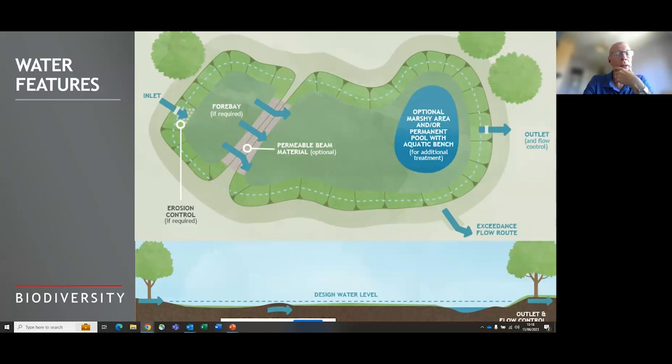Right. Okay. Chemically correct. They come in as in solution, but the two methods for nitrate are vegetation picking up nitrates to help grow, and they do need nitrates to grow, and also reduction of nitrate to ammonia, either by bacteria or by sunlight, and some absorption onto suspended solids. And phosphate is more or less the same sort of processes. And because the water is kept stationary for a longer period of time, the total suspended solids can settle out more. So your suspended solids on the outside of the dam is lower.